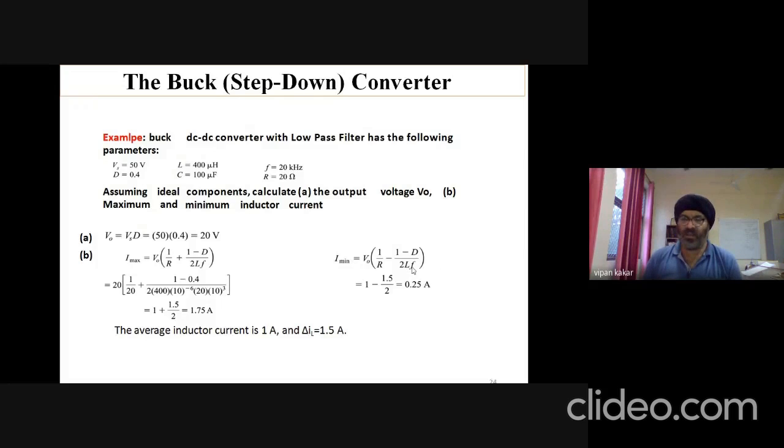So it means by changing the switching frequency, we can change the continuous current conduction mode into discontinuous, if possible, depending upon the inductance value. And if inductance value is made very large, I minimum is very small. So it can even go to discontinuous mode also, because if I minimum decreases by a large value, it can go to 0. So it can convert into a discontinuous mode.